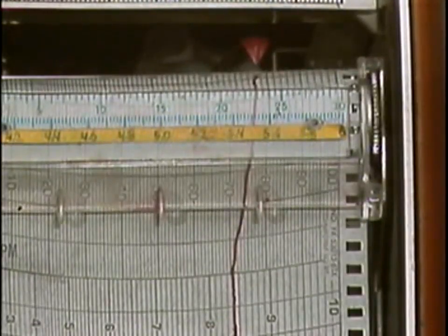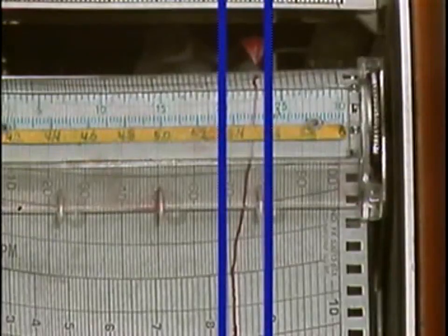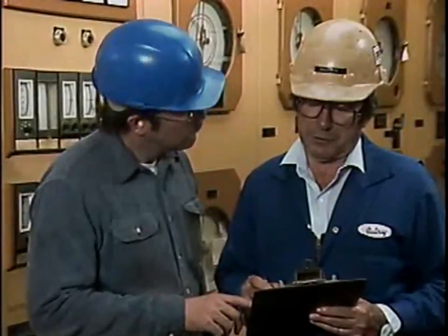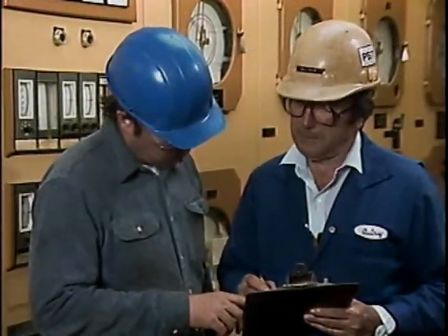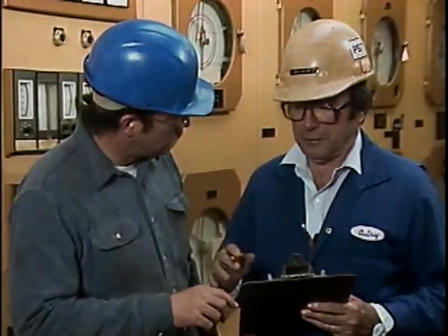For example, a steady increase in the compressor's cooling system temperature may be an indication of a problem. Operating records can help operators determine when actions need to be taken to correct problems. If you find a potential problem while you're making routine operating checks, report it as soon as possible. Take any necessary steps according to plant procedures to prevent damage to the compressor system.